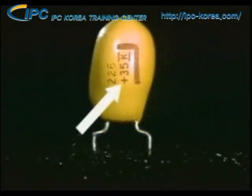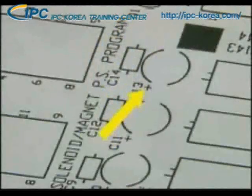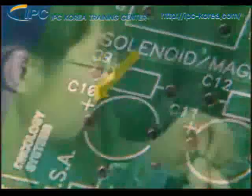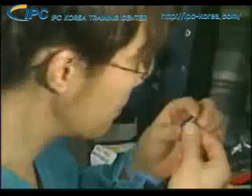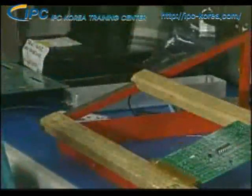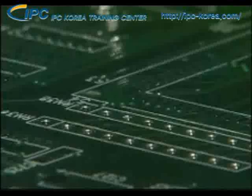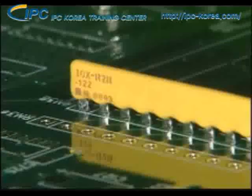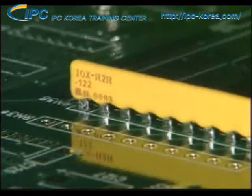A plus or minus sign is usually marked on the component as well as on the assembly drawing and on the component side of the circuit board. The direction in which a component is installed is also important for components with multiple leads, even if they do not have polarity. Proper orientation means that pin 1 of the component is in the same position as the pin 1 hole on the circuit board.